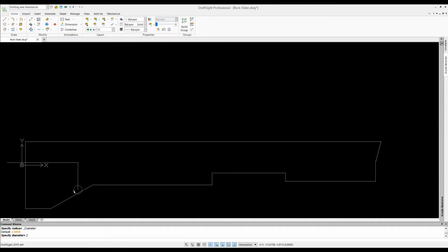That's okay. We'll trim that with our trimming tool up here, the scissors, later. So that's our first hole. We're going to leave that hole there. That's going to be part of the design, so that cutout will be permanent. So we know not to put a bolt hole there, obviously, because there won't be material there. So let's escape out of everything. And let's trim. So press enter. Let's go ahead and trim that off, trim that out. And that's good. And now let's delete these lines because we don't need them anymore.